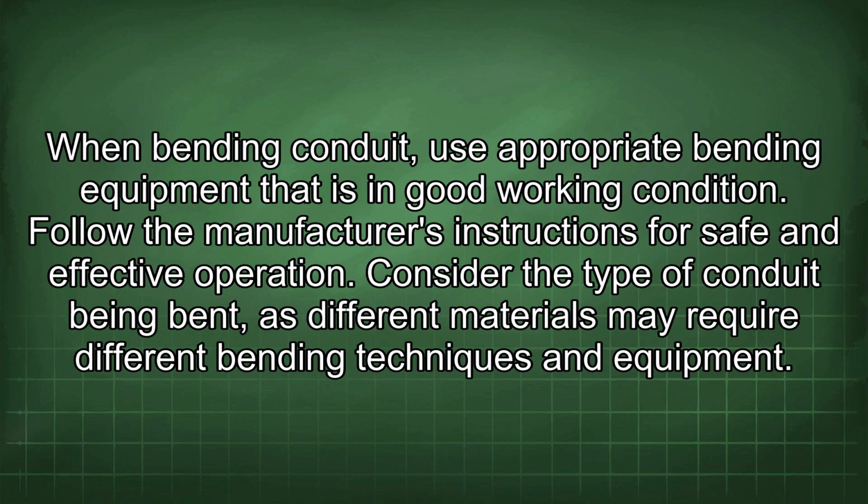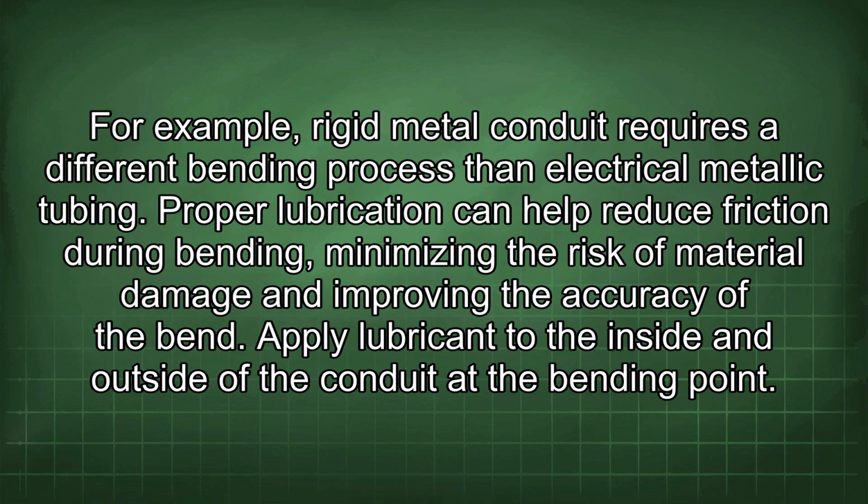When bending conduit, use appropriate bending equipment that is in good working condition. Follow the manufacturer's instructions for safe and effective operation. Consider the type of conduit being bent, as different materials may require different bending techniques and equipment. For example, rigid metal conduit requires a different bending process than electrical metallic tubing.